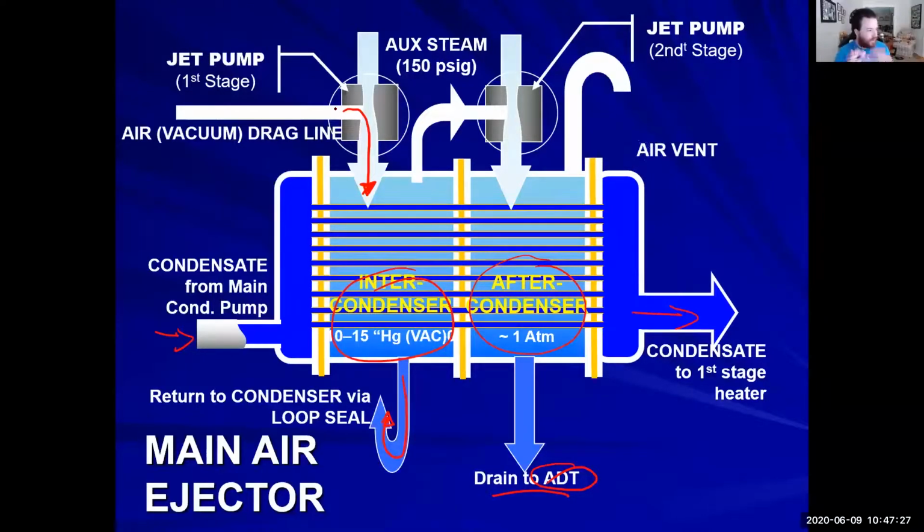Yeah, so nothing's going to be perfect here. But like 99% of the non-condensable gases are going to be tried to be pulled out again. All right. But that auxiliary steam and maybe a little bit of that non-condensable gas, this is why you won't turn this system off. Oh, we have perfect vacuum. We can turn off the main air ejector. No, it's just going to be constantly running. So any of that steam or non-condensable gases that gets grabbed here, that auxiliary steam is going to return to the condenser, and it's going to be condensed and turned into condensate and brought through.